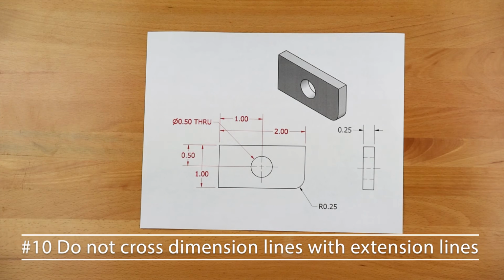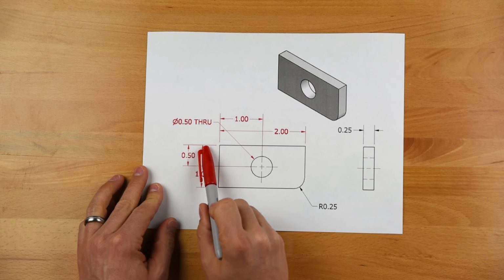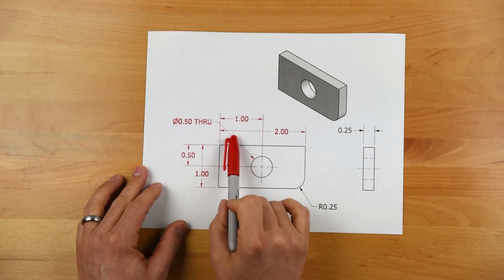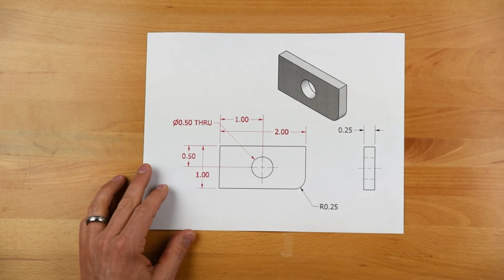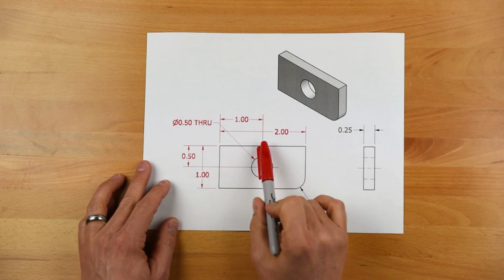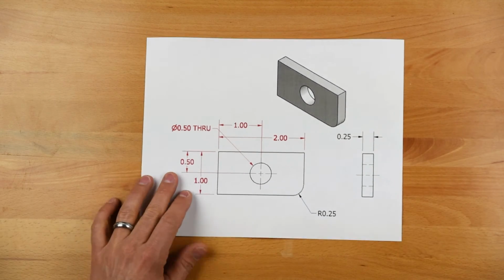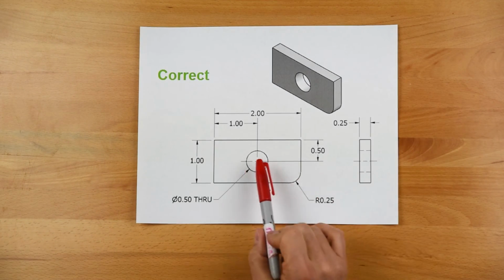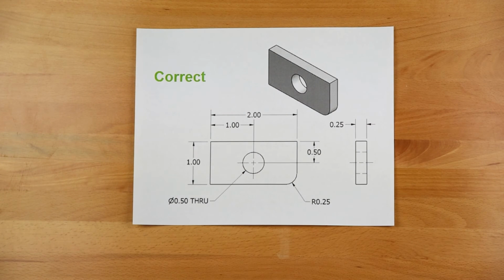In this particular example here, you can see what we're having problems with in red on this particular case, and of course what we have is dimension lines that are crossing dimension lines, and lead lines that are crossing dimension lines and lead lines. And what we really want to do is try to avoid this as much as possible. And so again, we're going to shift these around, essentially make them look a lot prettier, get these things moved around. What could that look like? Here we go. We're going to separate those out, move the leader line, get them into a place where things look good.